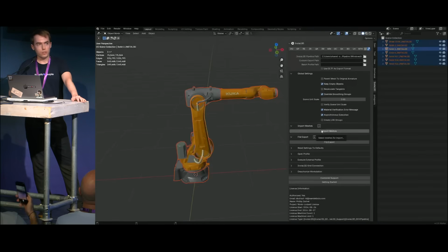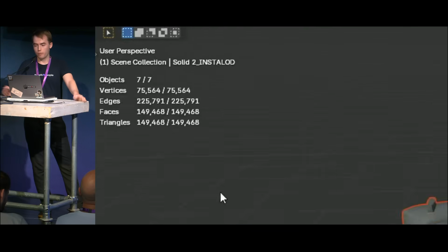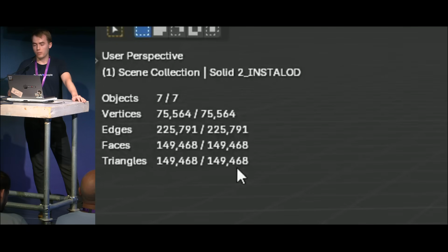Even after importing, the geometry most of the time is still absolutely massive. CAD models are designed for precision manufacturing, not for real-time performance, so the polygon count is mostly far beyond what we can work with, and optimization is just part of the process. So we reduce complexity for two main reasons. First, many of these models end up displayed in web applications, so for smooth performance there, we target a maximum of around 100,000 polygons, plus minus.